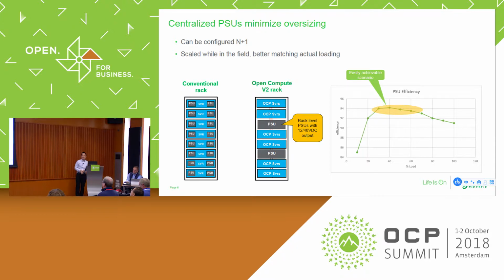And in the design, when you centralize your power supply unit, you have flexibility to change the whole loading, or put more servers there, again keeping them in the most efficient scenario. Typically we still have some redundancy, but if we configure as an N+1 model, with 2N input, you do not have 100% oversizing of the whole power supplies.